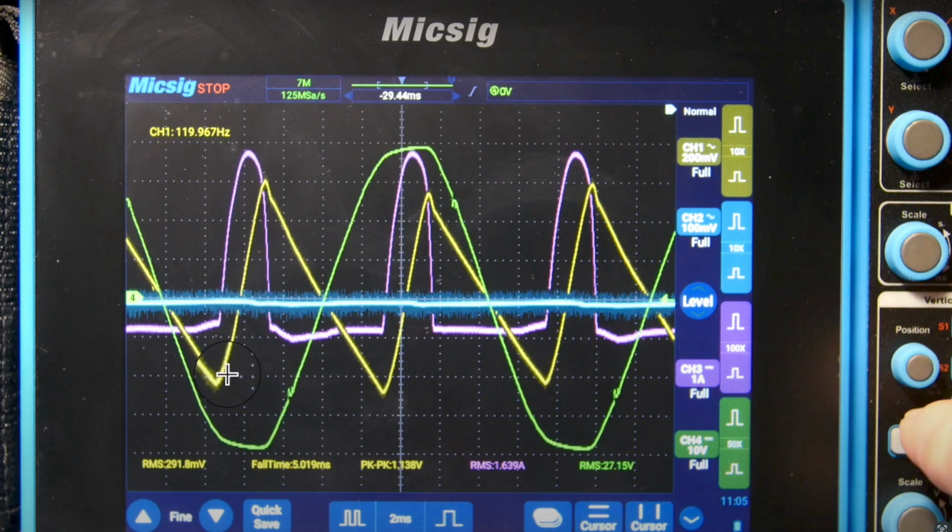Well, it's actually a little bit different voltage because see, each one of these waves is a little bit different. So if we set from here to here, that's about 1 volt, right? And then we could say, okay, the current changed from down here about 1 amp to up here where it's 1, 2, 3, 4. So it almost changed 5 amps during this same thing. So we could say, oh man, current changed 5 amps.